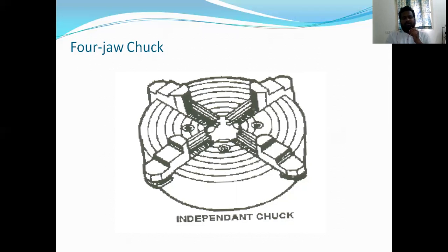And also we learned the thread cutting operation. In that thread cutting operation, we have to calculate the gear ratio. By the gear ratio, we get the movement of the spindle. With that movement of the spindle, the workpiece is rotated, and after engaging the half-nut mechanism, the cutting tool also moves in that way. By moving on the lead screw, the cutting tool cuts threads on the workpiece, right?